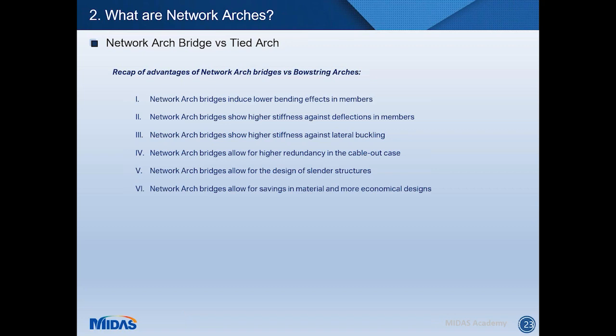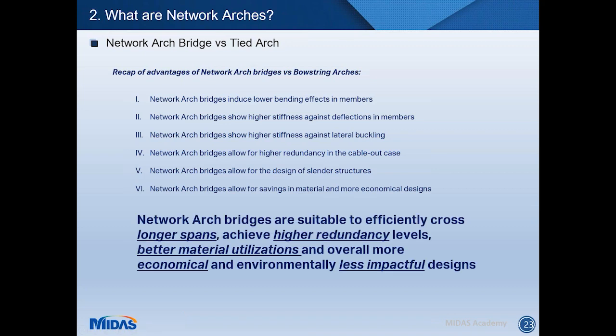This will allow us to design more slender structures and bring about savings in material, so it will make the structure economical. Effectively, the takeaway from this is that with network arch bridges, we can build longer spans that show higher redundancy, better material utilization, are more economical, and are environmentally less impactful as a consequence.